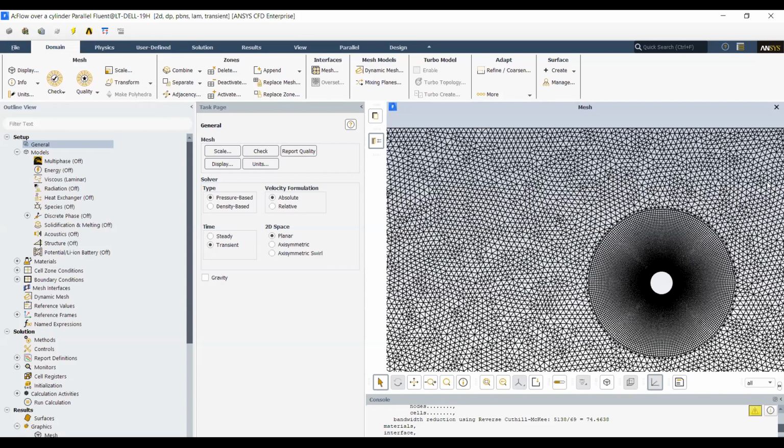If you have a fine mesh everywhere, then your solver has to spend that much extra time to solve those equations at the cell center for all those cells. So we need a good mix of balancing out the cell count and also having a fine enough mesh in the regions of high gradient so that we get an accurate solution.